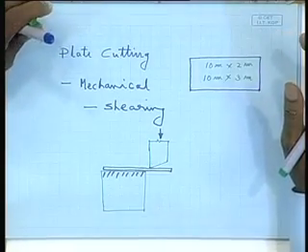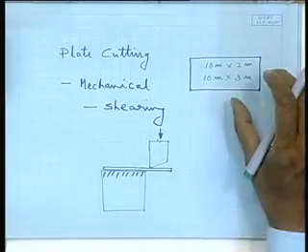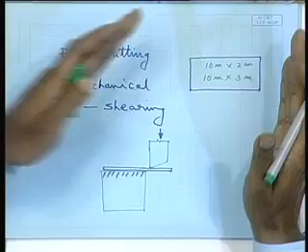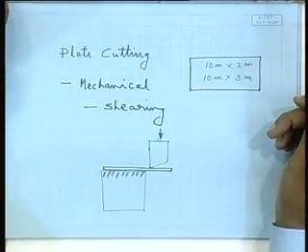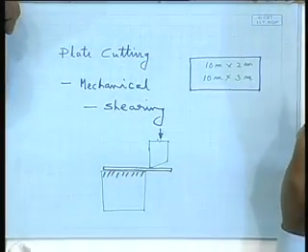The thickness variation could be at 0.5 millimeter interval up to a certain thickness, then 1 millimeter interval, then 2, 5, and so on. So you have plates of say 4 millimeter as well as plates of 80 millimeter, depending on your requirement. You get them flat, straight and of the standard size. Depending on your requirement, you have to cut it.